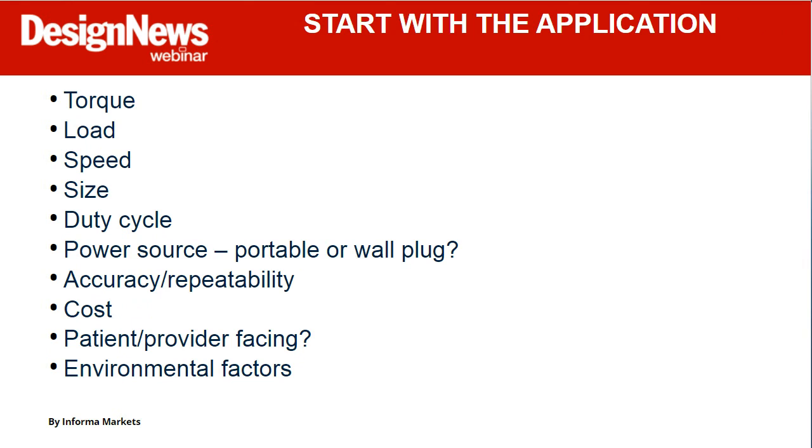Before really getting into any of the solutions, I always like to think about how you start from the design, and you've always got to start with the application. Torque, obviously. We've got to consider our load, not just mass, but also inertia. Think about the speed. Think about the envelope.